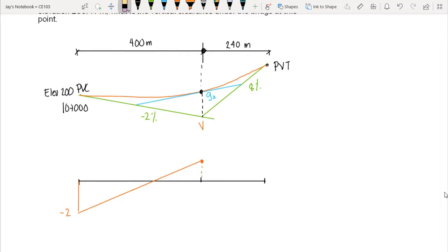Now the coordinate at this point is equal to the grade at this point, correct? However, we do not know yet the slope, G sub 3, at the point of the vertex, so we let this be our variable G3. Later we will solve for the value of G3 because we need it to compute the location of the lowest point.